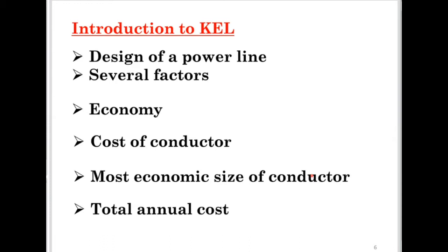So when we have a power line, we said that in generating stations, we have a number of generators operating in parallel, and from those generators, we connect a step-up transformer to increase the voltage to a very high level to reduce the current, hence reducing the power losses that might occur in the transmission lines. Now the power is on the transmission lines.